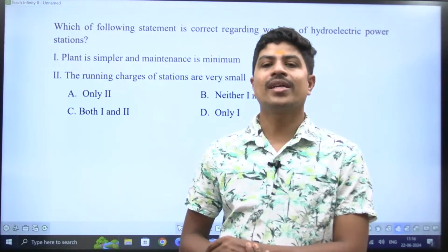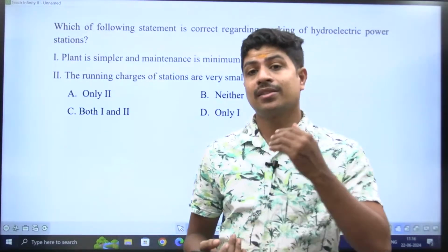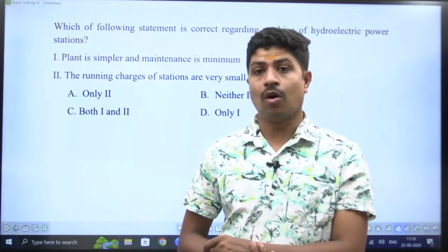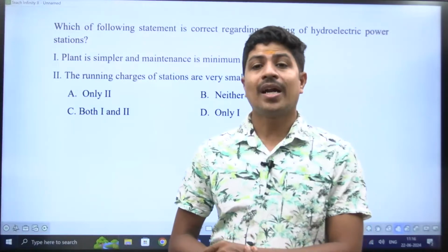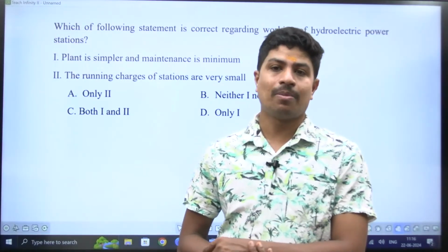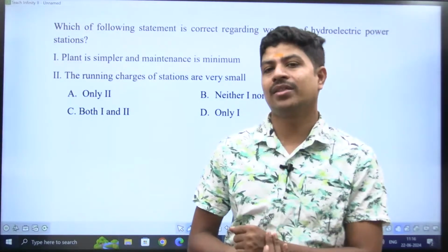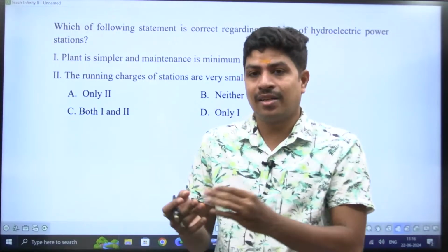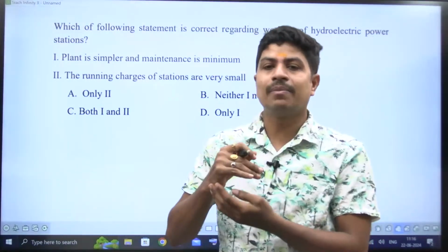What is a base load plant? A base load plant is a plant which can supply power continuously at low cost. This means the rating of the base load plant must be huge, right? And the cost of power production should be less. Plants like a diesel power plant or gas power plant can be used as peak load plants. If all of a sudden the power need increases, then the diesel power plant can easily be connected to the grid within less time.